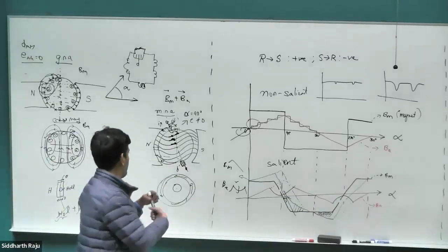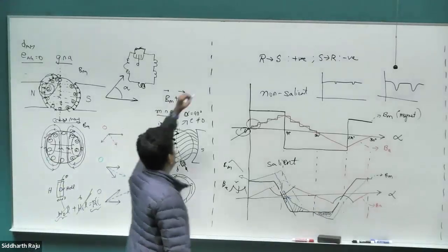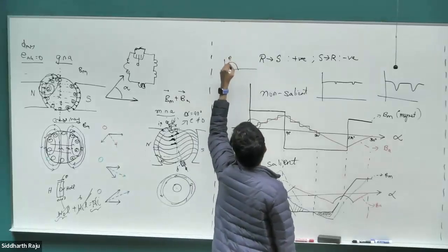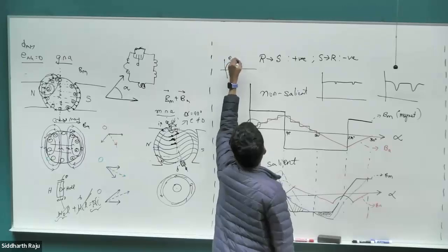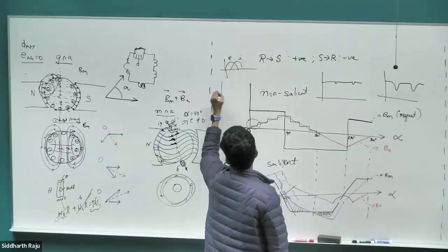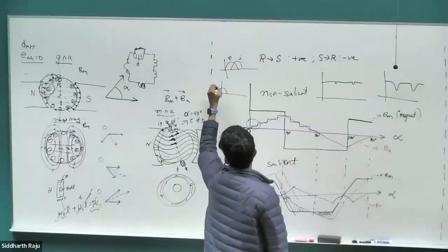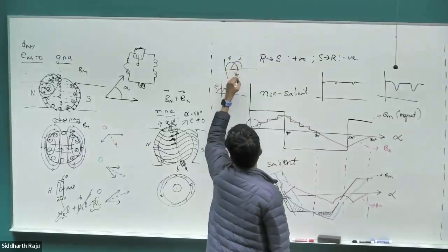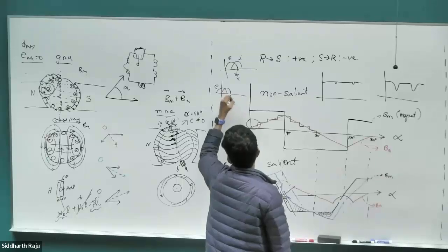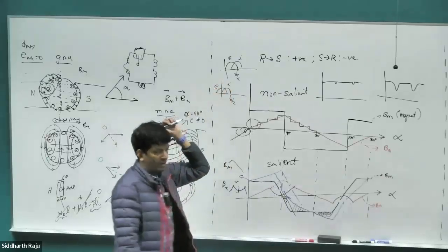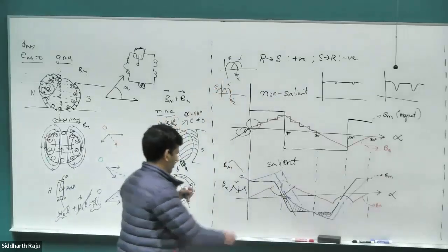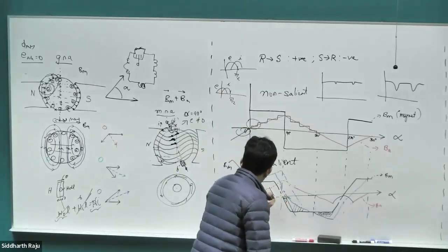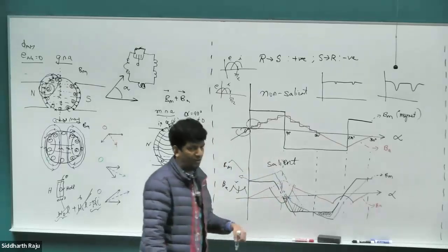If you remember, we looked at the case where our EMF, if this is our voltage and our current is phase delayed, right? But if we shift our EMF backwards, then our current is also shifted backward. Let's say this was pi by 2 before. We can make our current go to 0 at pi by 2 by shifting the EMF backwards. And how do we shift the EMF backwards? Why just stop at 0? Why not make this coil generate a negative EMF by making the magnetic field go even further negative?